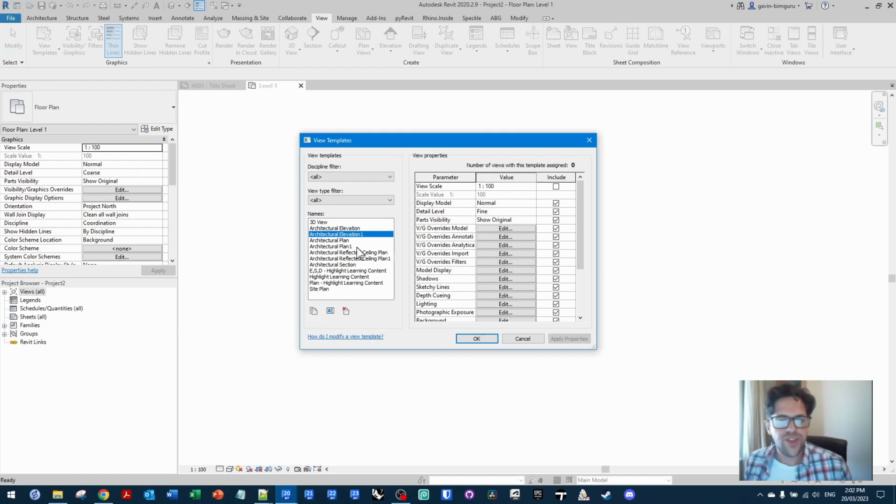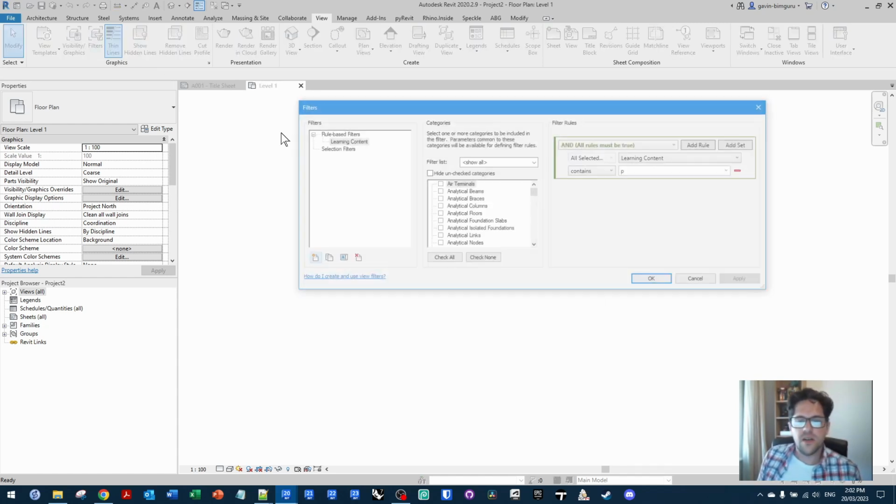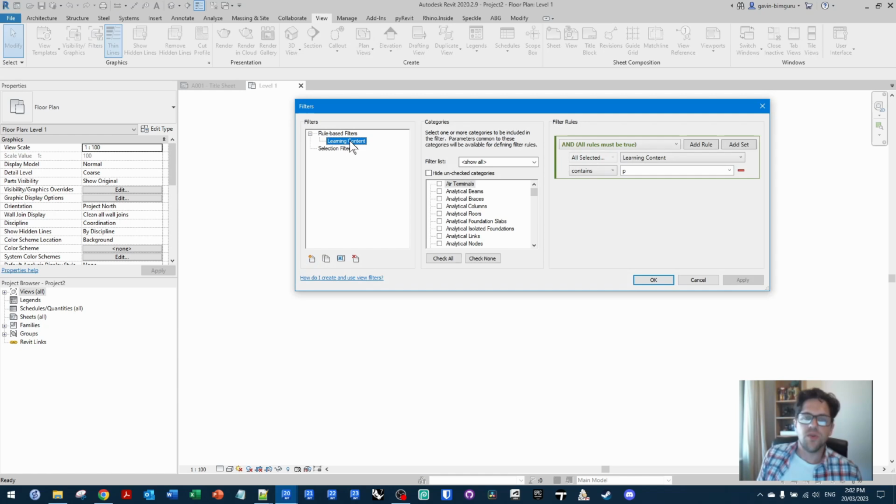So you could also run a check before you actually send those elements to the UI and say, is there something that already has your name in the model? And maybe you might want to filter it out, or you might want to change its name to have something different in it, for example, underscore copy. But in this case, you can see it also does transfer sometimes objects across as well. I've also noticed a filter came across with one of these view templates. So it does bring across a majority of other objects that may depend on it. It's going to vary depending what you're copying.